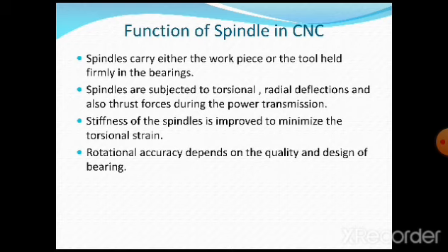Whenever we use spindles on which the workpieces or tools are mounted, the workpiece especially is subjected to thrust forces due to the machining operations. So the spindles should be designed in such a way that they can sustain all these types of deflections. That can be achieved if the spindle bearings are properly mounted on a CNC machine tool.